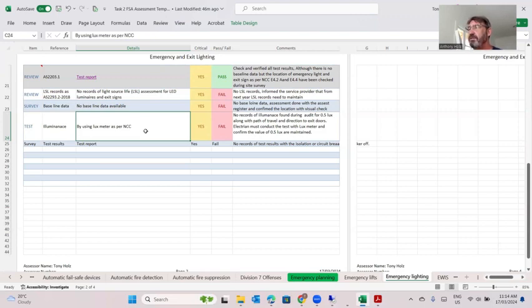You cannot turn off artificial light, even the natural light. Natural light's always coming into rooms. You cannot determine performance of a system based on doing light lux testing. That's why it's critical that the amount of lights and the type of light is installed in the correct places in order to satisfy that design.